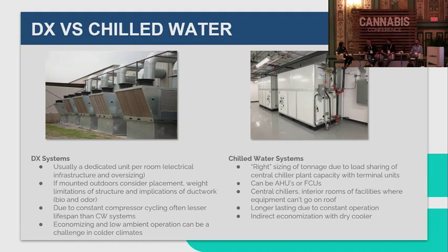Yeah, I'll add from my perspective, there are some nice advantages to DX systems, especially simplified DX systems. Cost, they can be much cheaper. Familiarity, you got a lot of technicians out there that know how to work on a packaged rooftop or standard comfort cooling DX stuff, just because they're so common, and redundancy. But Haley, thinking of it from an engineering perspective, when you're laying these things out, what are you discussing with clients, and what are your thoughts?